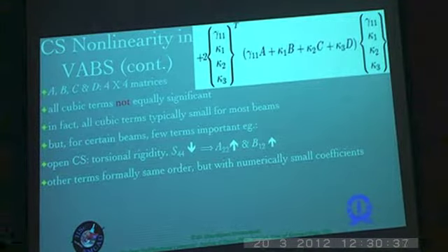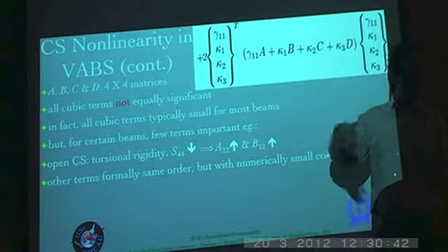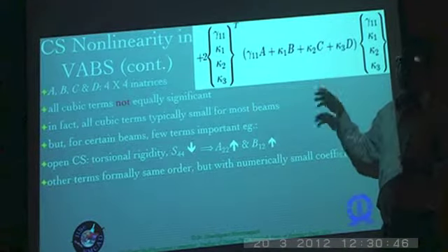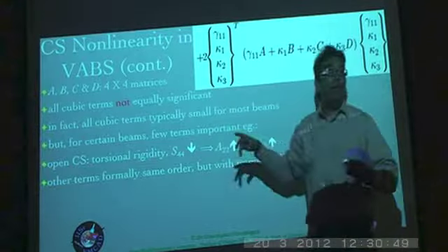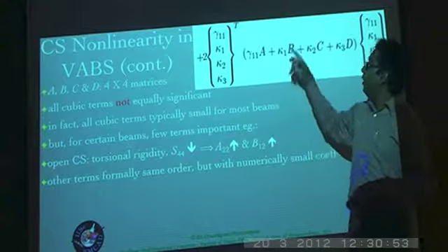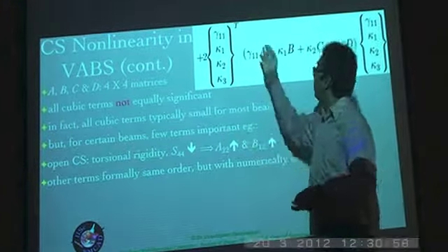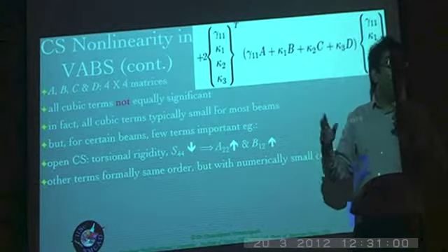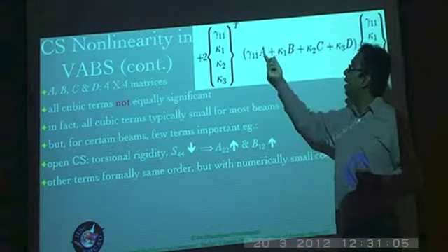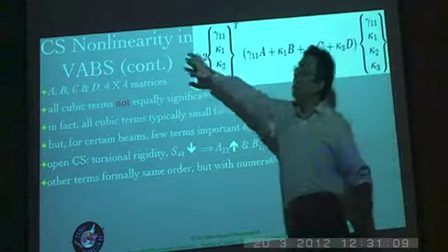Then next, other terms. Again, there is no unique way you can express this particular thing. There are many other ways you can express it. This is just for convenience, we are putting it in this particular fashion. The same energy U and D can be obtained by reshuffling these elements in some particular way. Because, for example, the contribution of a gamma 11 into kappa 1 squared can come through many of these terms, okay? And they can be divided between these. So there's nothing sacrosanct about these matrices A, B, C, D. What is sacrosanct is the U and D that you get out of it.